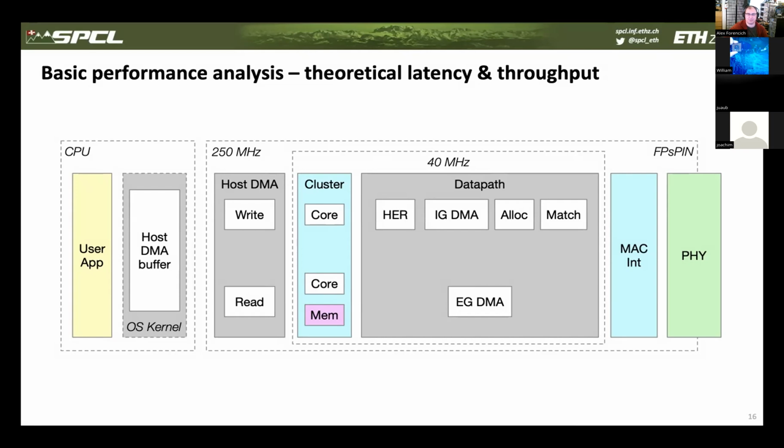That's true. But for the segmented interface, one of the reasons I did things that way is you can just drop down a dual port, dual clock RAM and then run at whatever frequency you want. The RAM itself will give you the CDC. I don't take advantage of that in Corundum right now, but it's absolutely possible. You can run your internal interface at whatever speed you want, and you don't need any additional CDC logic at all because the RAM itself gives you the CDC.